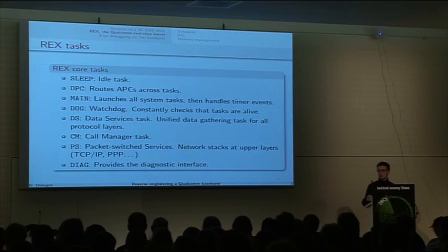The main task is the first task loaded, the first task created. It creates all the system tasks and then handles the timer events. There is also a task which is used to verify that critical tasks in the system are still alive, a watchdog.